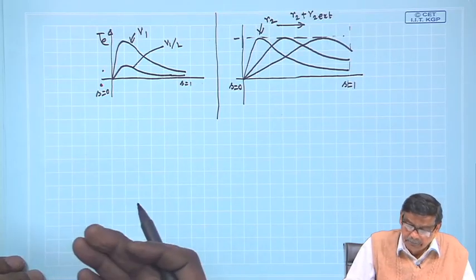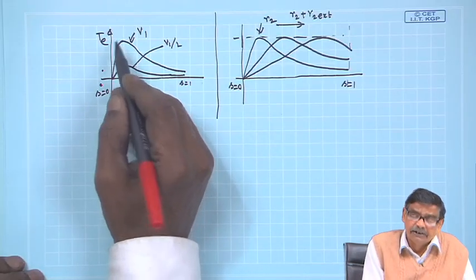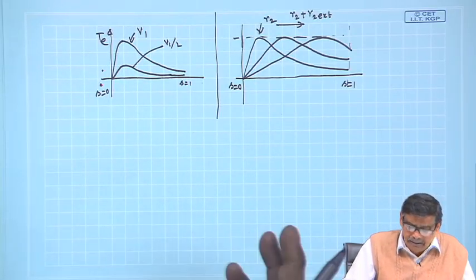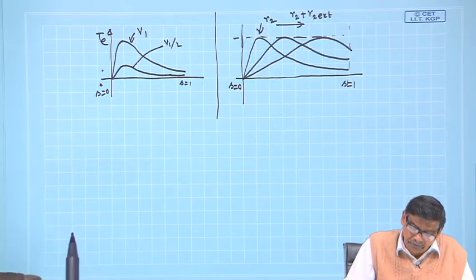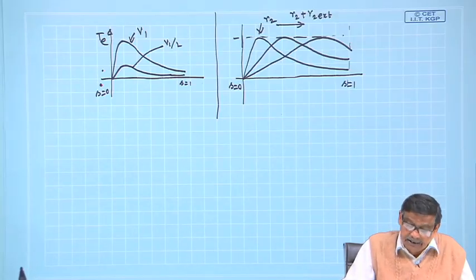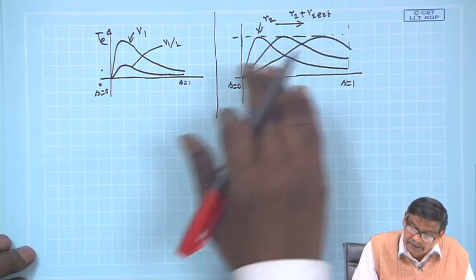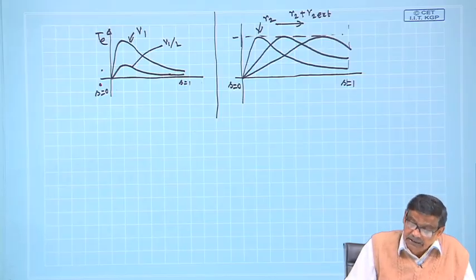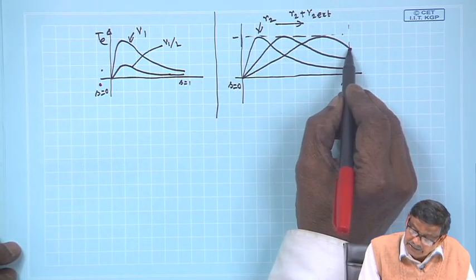Maybe reduce the supply voltage, which is not done very much, because you then sacrifice T max to a large extent, and therefore it reduces the capability of the motor to supply any substantial meaningful load torque. Okay. And another thing is, you can play with the rotor resistance,